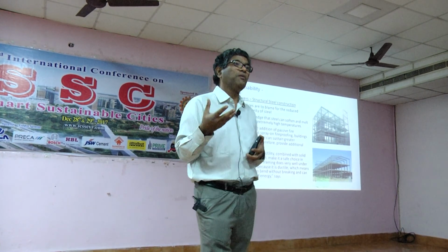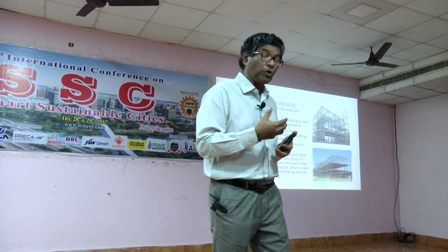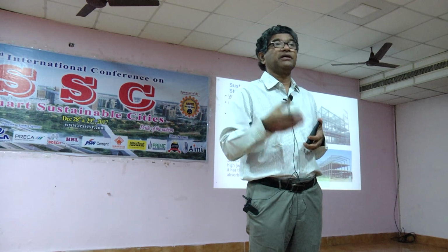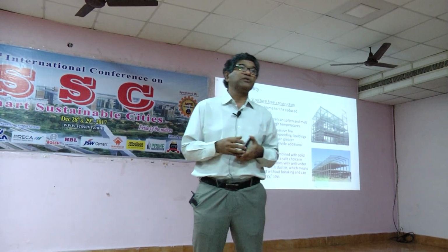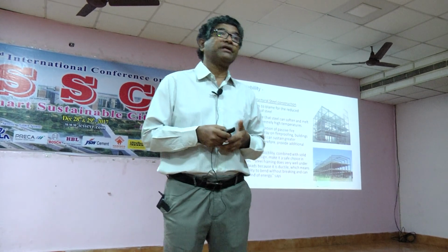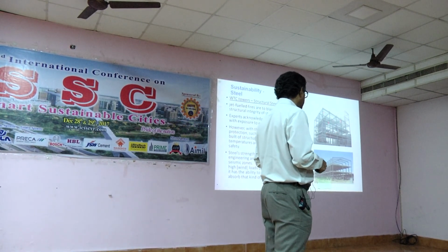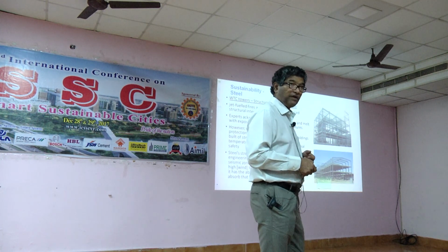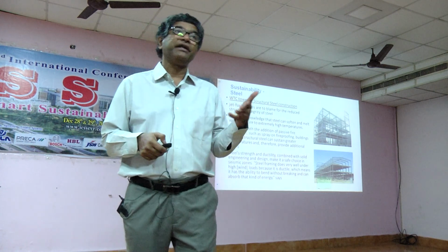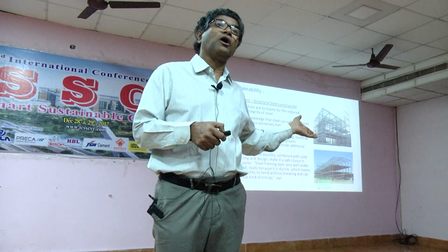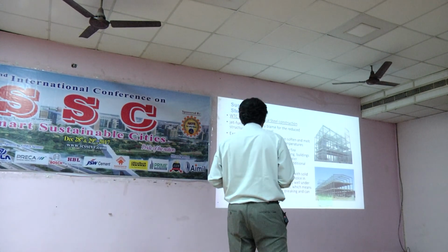Okay, steel is a wonderful material. Its strength to weight ratio is fantastic compared to concrete. For a span of about 20 meters, I require a huge concrete beam, but with steel it will be quite less. Right? So much depth is not necessary because the strength to weight ratio is fantastic. But again, you need to protect it from fire. You need to give sufficient protection from corrosion. Otherwise, the steel, which is manufactured from iron, will go back to its original compound, iron. So you need to protect it from corrosion as well as fire.